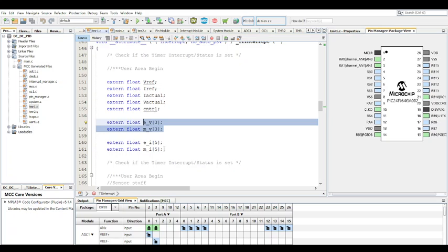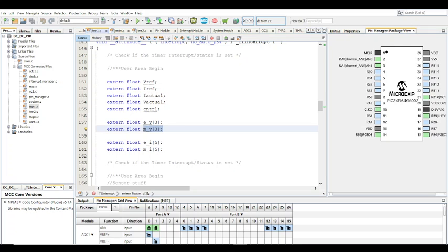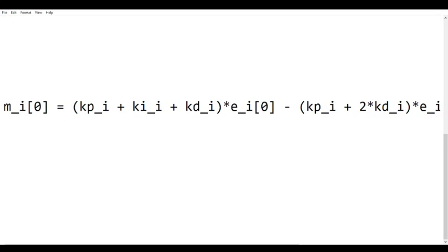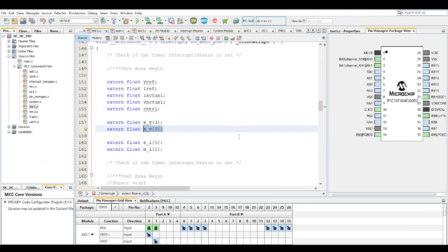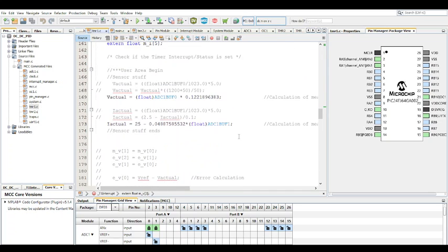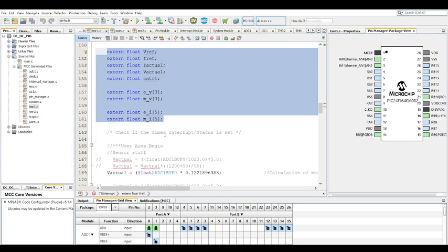Constant voltage control, and this is the array for constant current control. So this is for the error. This is the error array, and this is the output to the step, the PWM step. So in this case, it would be this. It represents this, or in traditional terms, I guess, this PID input. That would be for the PWM that's going to the converter. Alright, so that's that. This has been initialized in the main, so this is why it's external everywhere there.